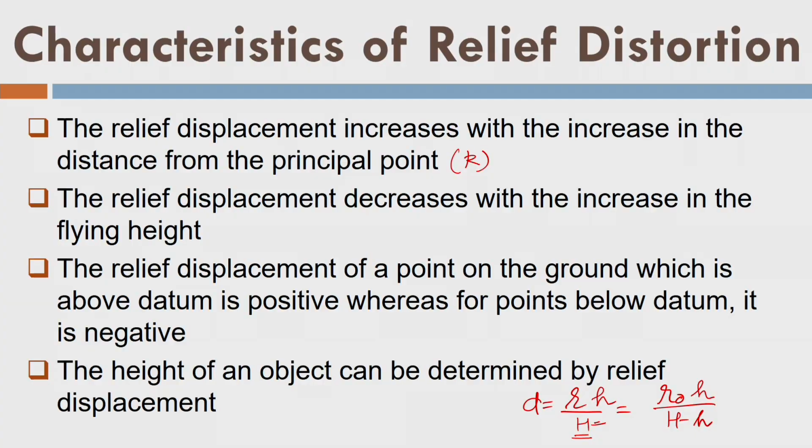If in the aerial photograph we define the relief displacement with this height h, in the case of a satellite I will put this h equal to 750 kilometers or 900 kilometers, whatever the height. As a result you will not find any relief displacement in satellite images, and that is the best source. That means the satellite images are the best source for planimetric mapping.